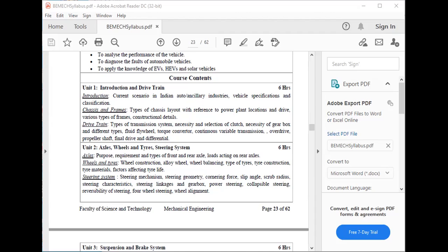This is the hydraulic clutch. It uses the master cylinder and slave cylinder. It uses the brake fluid and it needs bleeding. Hydraulic clutch has no complicated linkage, and it can easily control mechanical advantage with piston sizes, and servicing is similar to hydraulic brakes. Multiplate clutch is also available.